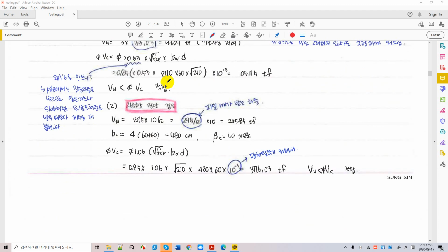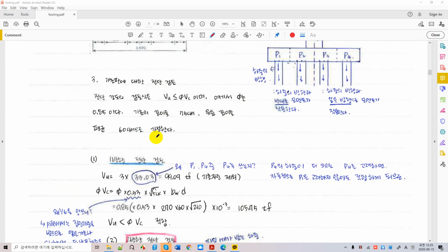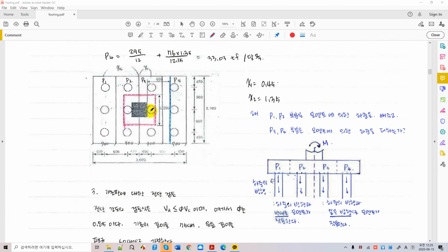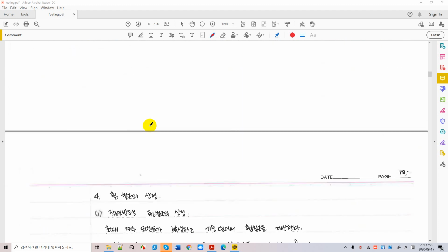All right. So the entire punching shear is calculated on this, right? And then the critical failure is this 66. And again, it is d over 2 from the face of the columns, and I'm not going to repeat that.